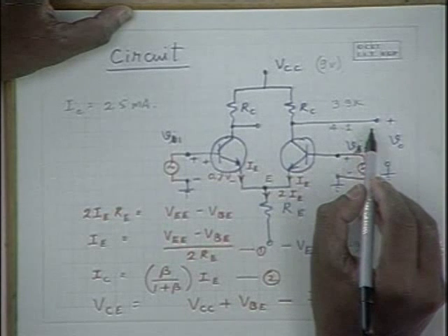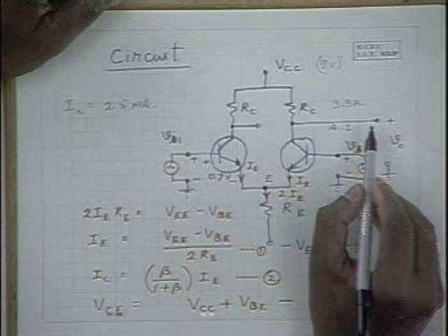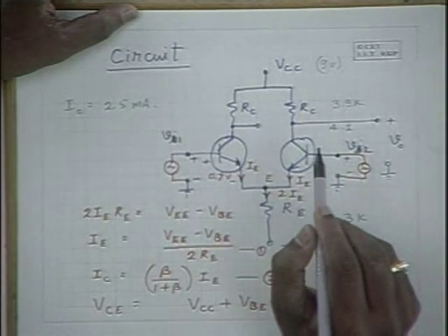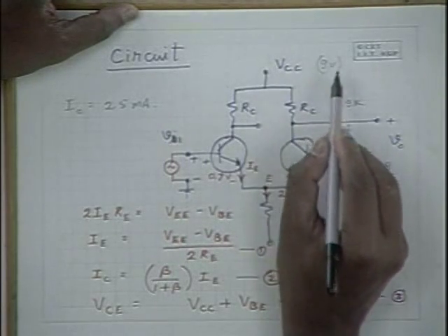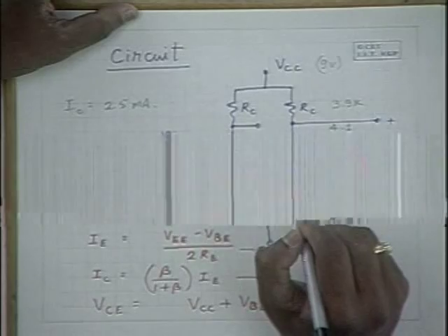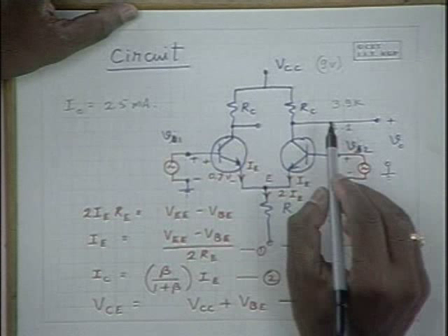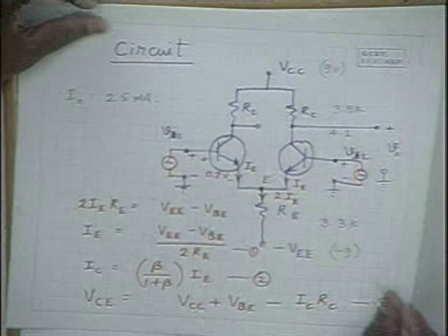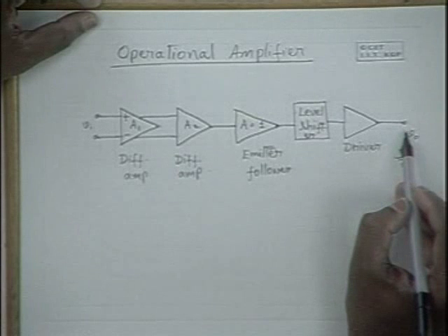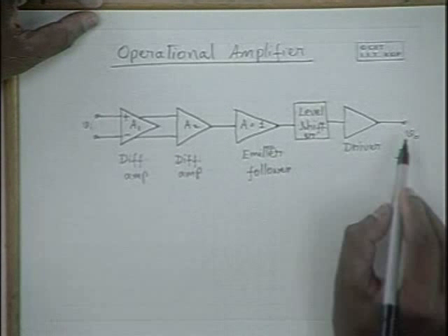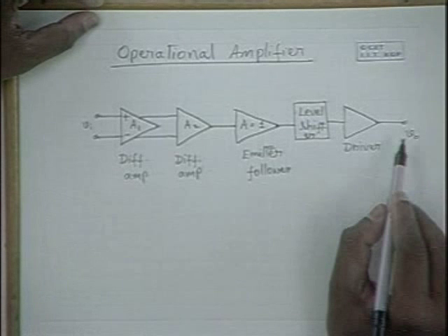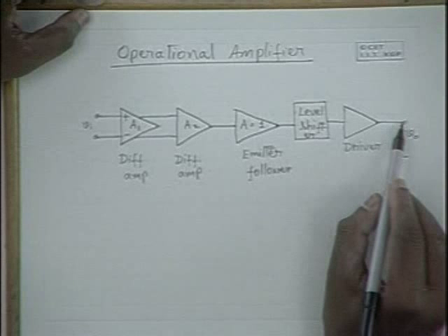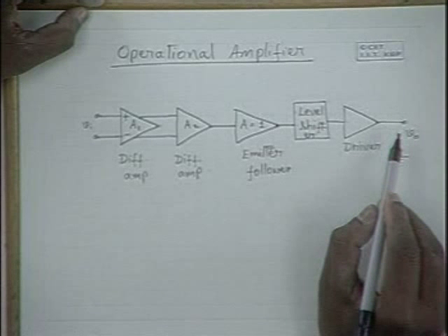And this voltage is not biased to be 0, because it becomes difficult to bias it around 0. So if this is a 12 or 9 volt supply, this may be some 4 volts or 5 volts, something like that. But when we take the signal output towards the end of the amplifier, for a 0 DC input, the output voltage should be 0.